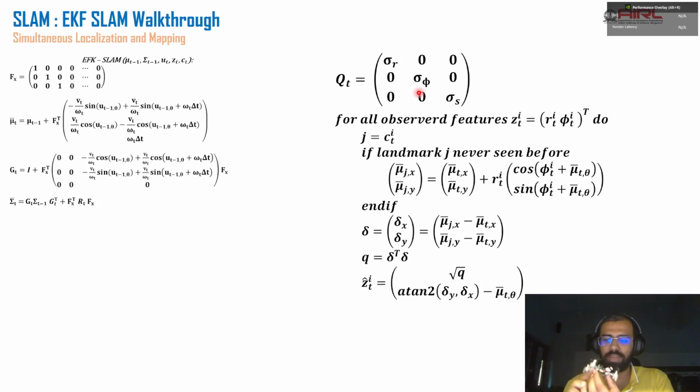The small drone has a range finder, and this small drone is going to estimate, given its own position, how far each obstacle is from it using the range finder, which continuously spins. So from here, you will get to know what the range is, how far that obstacle is from this robot, and at what heading. So if this robot is moving this way, this is the heading, the bearing at which it found that obstacle.